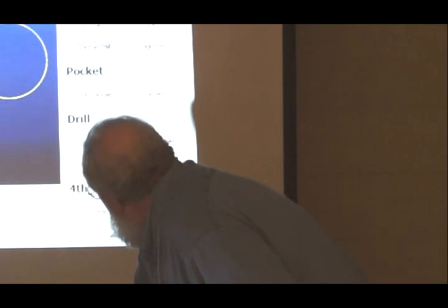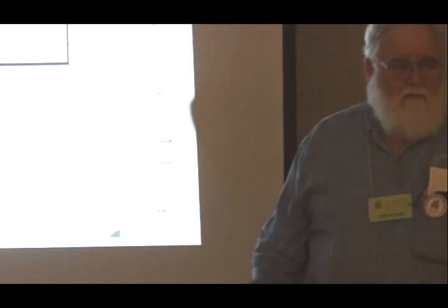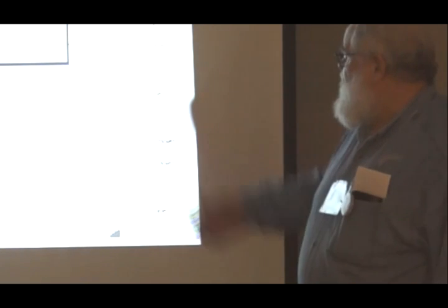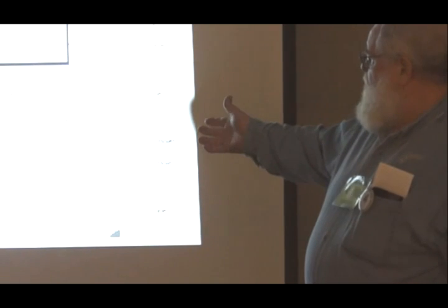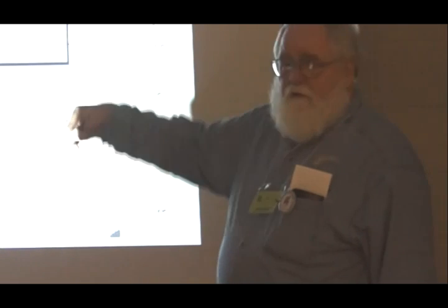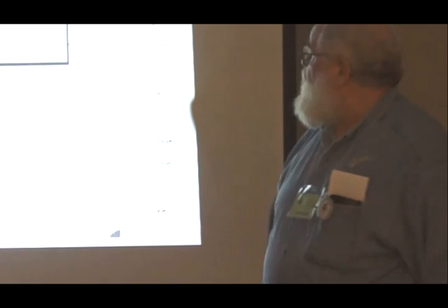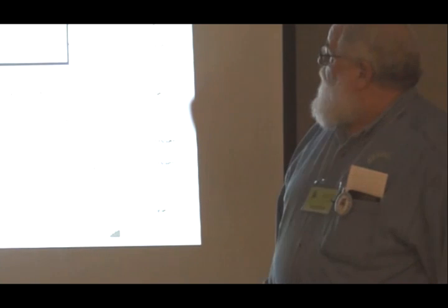Now in drilling operations, we got really kind of carried away here. The obvious bolt circle, everybody needs a bolt circle. And you can have as many, whatever diameter, whatever number of holes. You can specify a starting angle so it doesn't have to start; normally it starts at 3 o'clock.